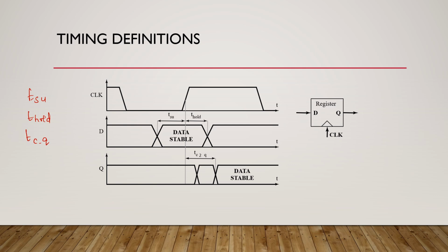See here, here we have the setup time, here we have the hold time. Okay, this is my input data, this is my output, right? So in the register we have input, output as well as clock. Depending upon the clock, the output will be connected to the input. That is, the register can act in transparent mode, another one is hold mode, right? It is a positive latch, so transparent means clock is 1 and hold mode is clock is 0, right?